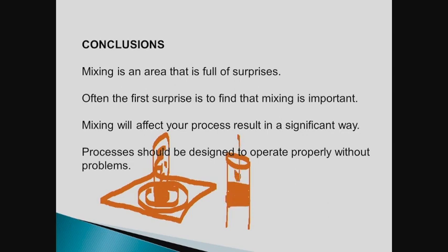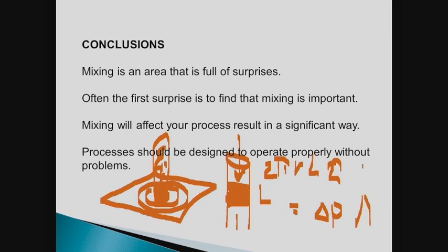You put higher pressure here and low pressure here, and you know the length of that, and so you do a simple force balance, 2 pi r L. The yield point, which we'll write as tau, times 2 pi r L equals the pressure drop times the area. And this is the yield point. This is what you're after right here. That would be an example of a plug tube test for a yield point.